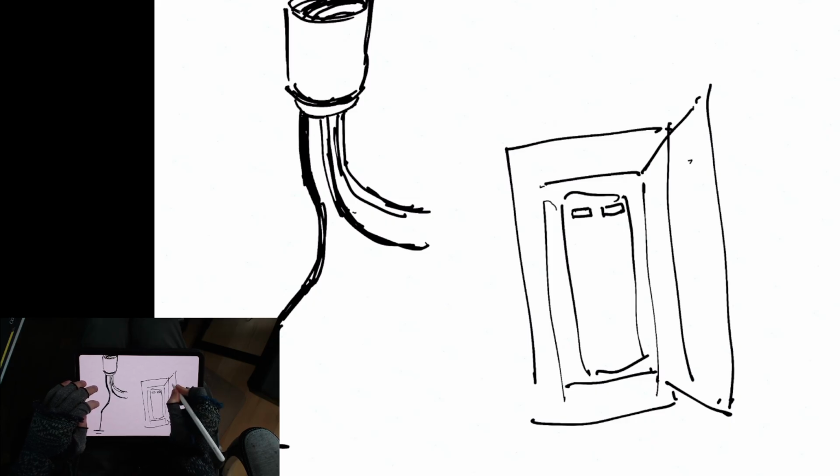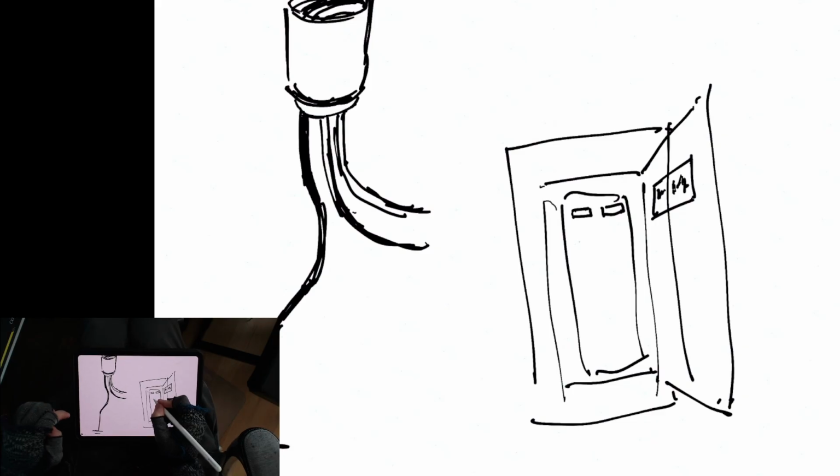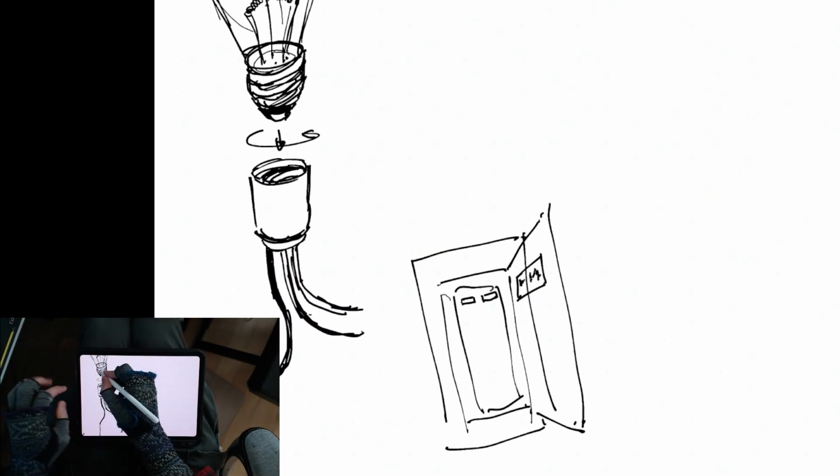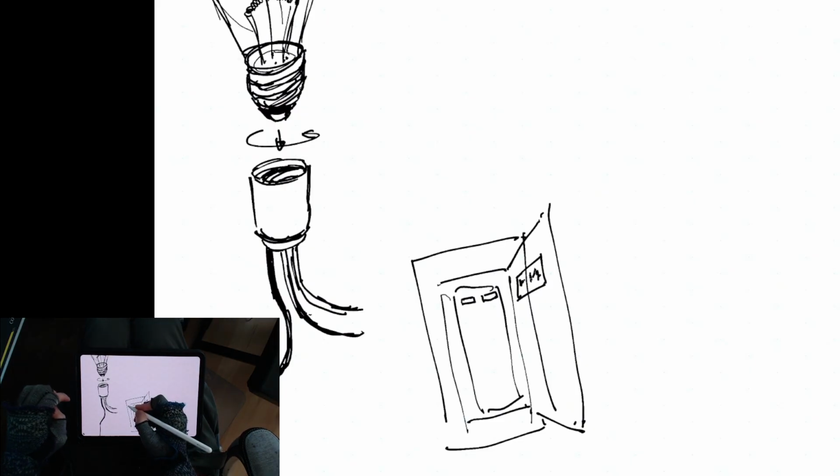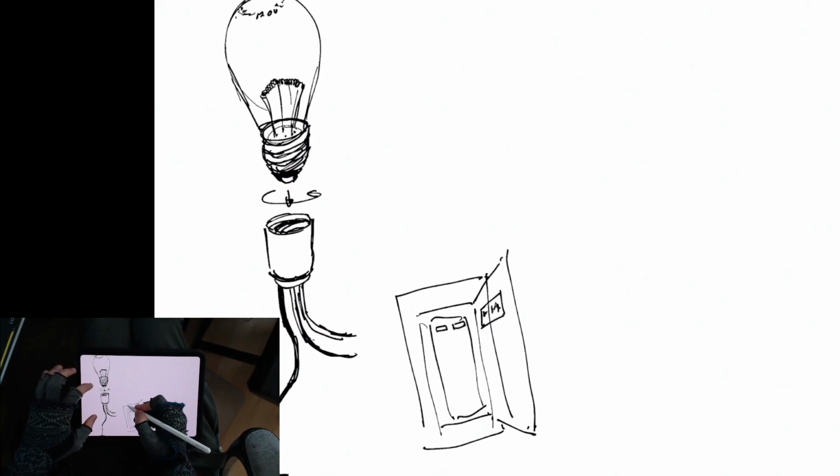And of course, in your fuse box, you may have little labels that actually say, this is for kitchen light, and this one's for like the stovetop and that sort of thing, right? In fact, you may have several lights which are all hooked up to one single breaker. So if you have enough things connected to that one breaker, all in the same circuit, you might overload that breaker, and then the breaker will trip. Or if it's a fuse, you'll blow the fuse. Interestingly enough, the fuses have the same screw type mounting lugs as the bulb does.